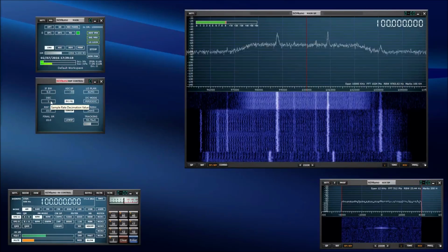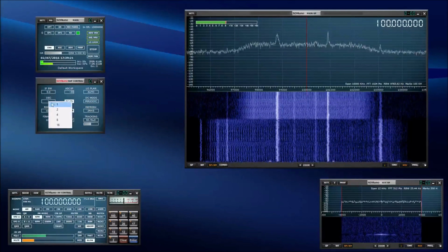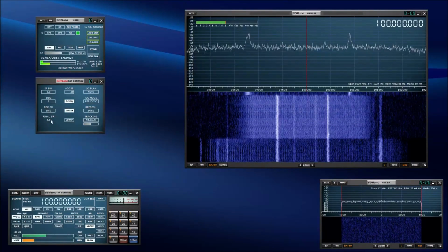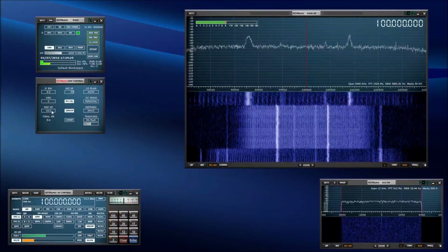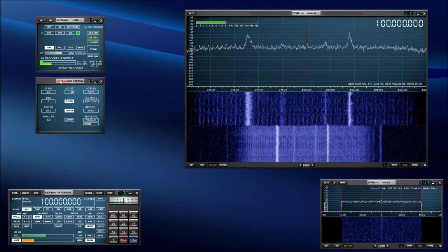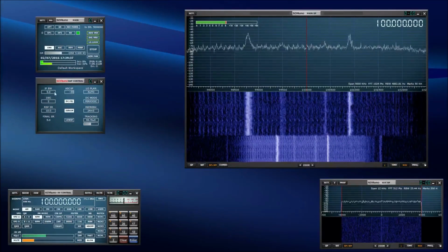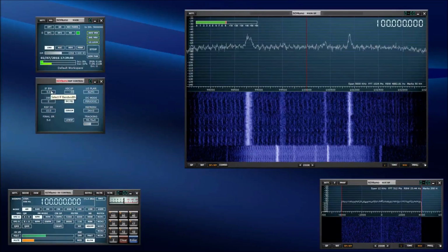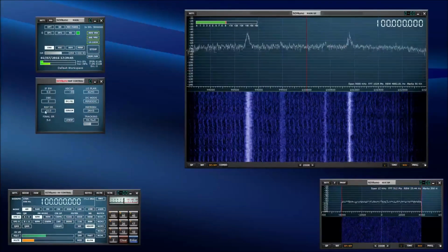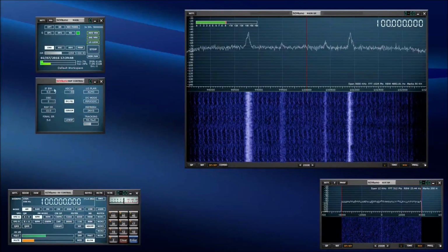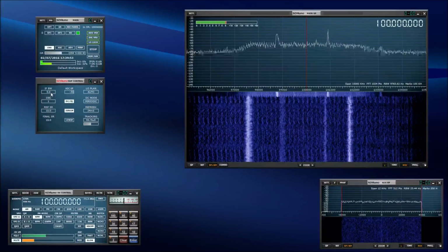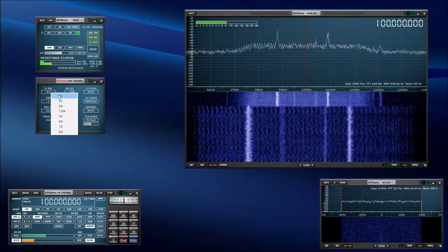Here I could specify a sample rate of 10, but I can now specify a decimation factor of 2, so my final sample rate is 5 megahertz, and that is actually better than specifying a decimation of 1 with a sample rate of 5. So there's a lot of flexibility here in terms of CPU load and noise performance. I would suggest you have a play around with some of these values to see if that gives you better performance for your application.